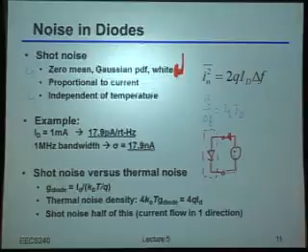Okay? So if I do this experiment, just like with all of the analog designs that we do, at some given particular bias point, I could always measure what the effective conductance, small signal-wise, of that diode was, right? And just like we said with bipolar junction transistors, because it's an exponential relationship between current and voltage, when you take the derivative, in other words, you find that small signal relationship, you'll again just get something that's proportional to the drain current in the first place, divided by kT over q, right?